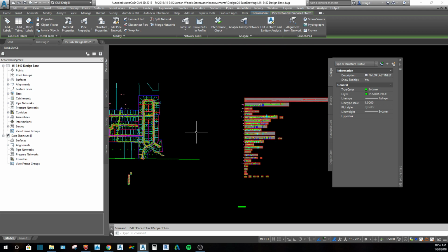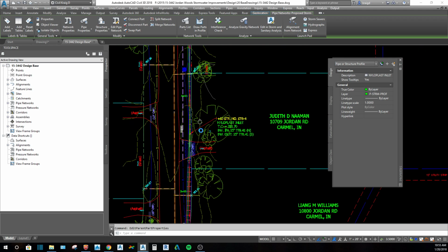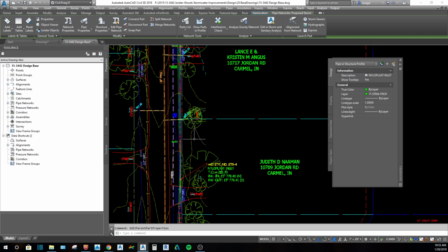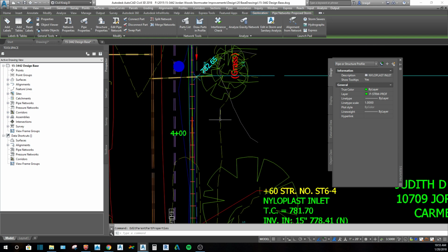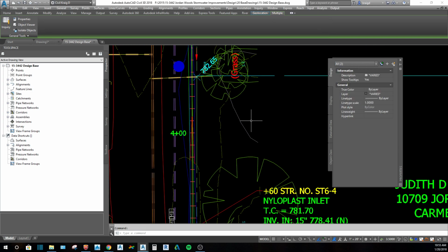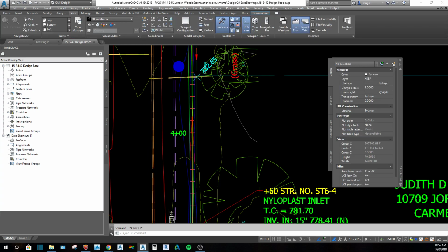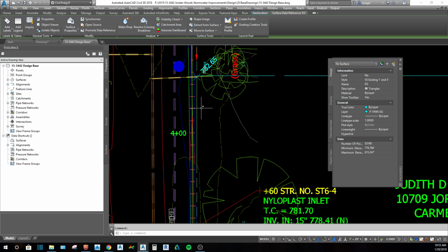I was going to look at some surface styles. So, labeling contours. You click on the contour. It pulls up in your ribbon the button to add labels, which pulls up another box somewhere.